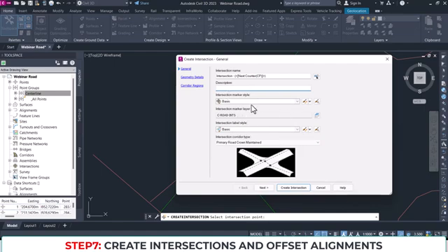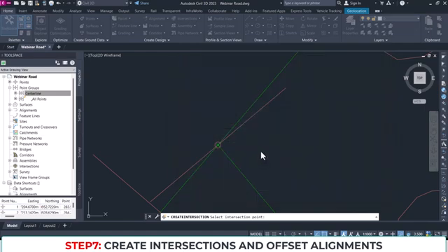You can always create your own default views if you want, but basically leave everything by default. This is an intersection where the primary road, the main road that is traveled at 100 km/h, is crowned, while the other one will just be joining it without being crowned at that intersection. But if both of them were roads driven at 100 km/h, I would select this option: all roads will be crowned, so it will be crowned at the center. For now, since the primary road is at a higher speed, I'm going to select this one. So let me create an intersection.